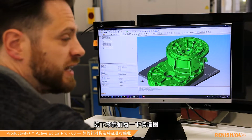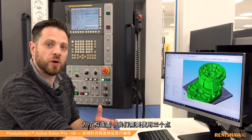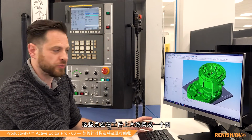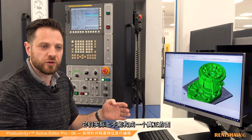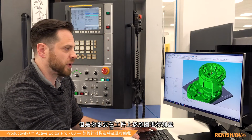The next one we'll look at is the constructed circle. So to be able to construct a circle, we need to do that from 3 points that approximately sit on a sort of circle that we have on the part. So an example might be where you've got a series of arcs that don't actually physically make a circle, but you want to measure it as such on your component.